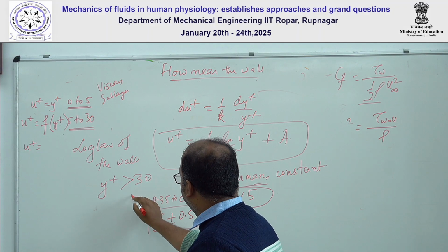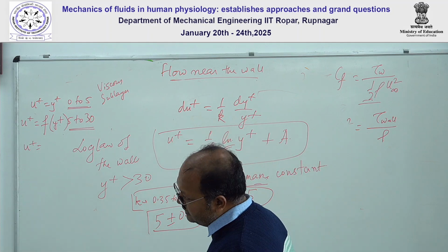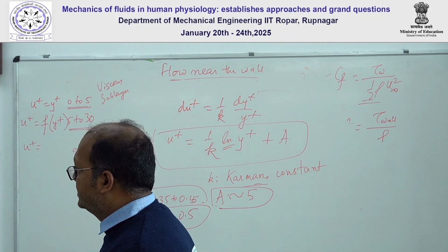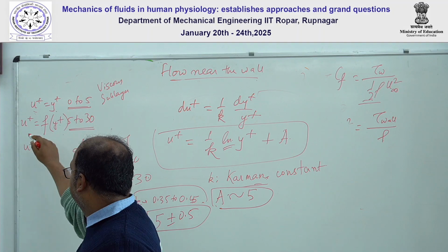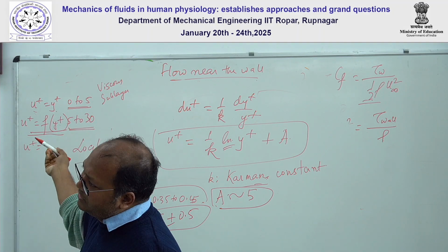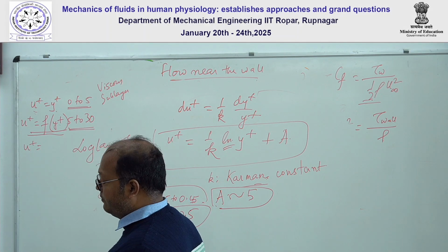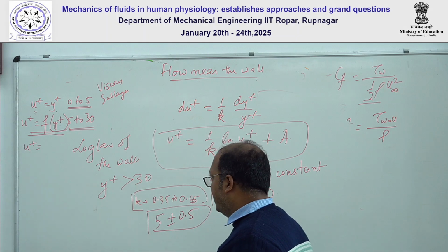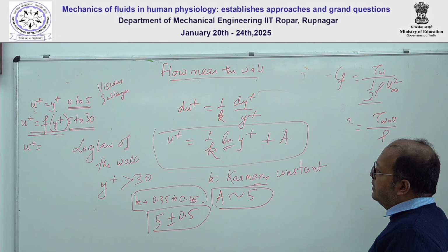These are the guidelines based on which you can carry out the calculation when someone tries to simulate the flow near the pipe wall. Near the wall, we know the formula u plus equals y plus. In this region there is some sort of scaling relationship; if you do a literature survey of flow in different domains, you can find the scaling relationship. Some people have given a formula, and in this log region this is the governing formula.